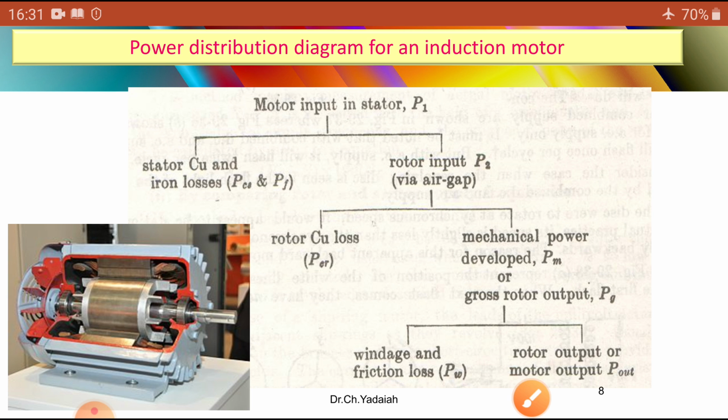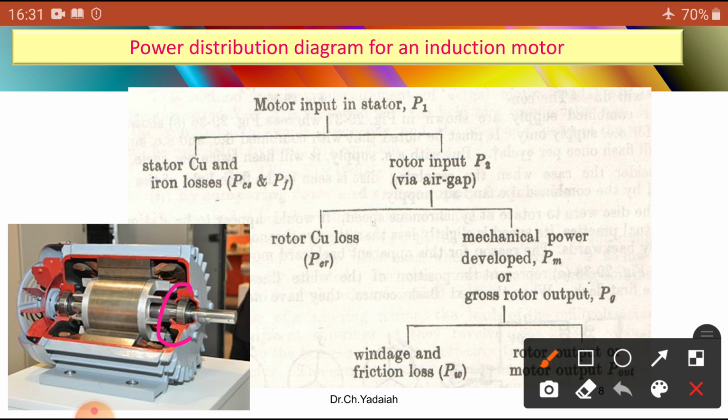You can observe the parts present in the motor, all of which take some power. You can see here one bearing is provided to reduce the friction and windage losses, otherwise more losses may occur. To reduce the iron losses we have laminated the core materials.